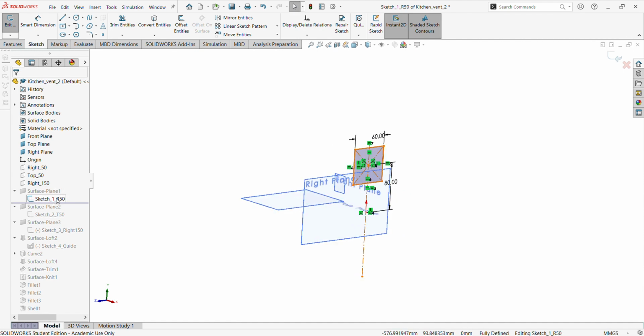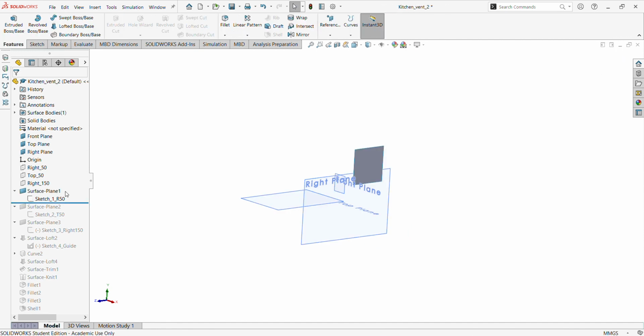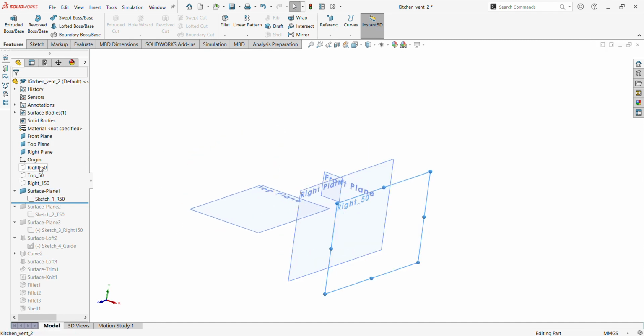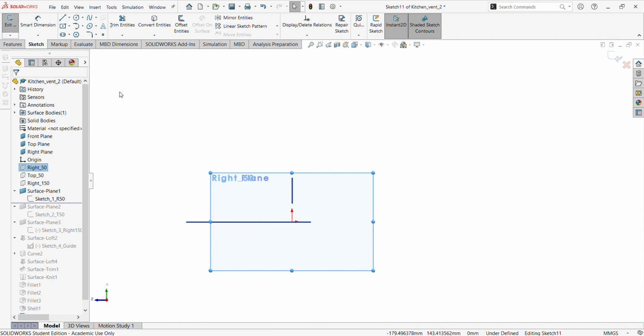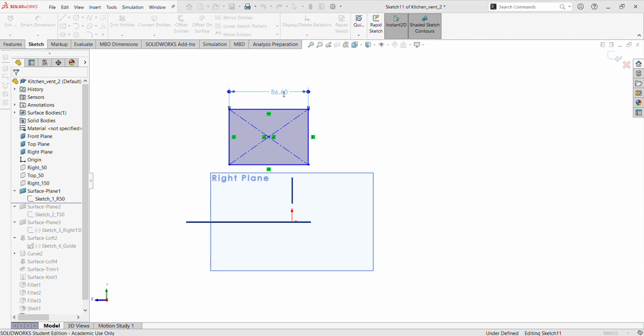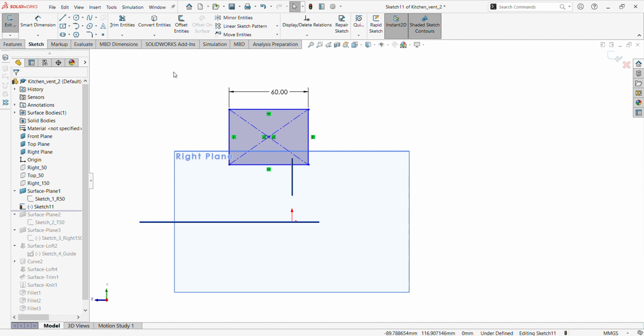If you wonder what I've done, I simply go to the offset plane. If I hide this sketch, you see quickly what was done, so we can save time. Hide the sketch. Okay, that one was not yet hidden. Just go to the plane here and create a new sketch, dimension it to 60, and make all the sides equal. Then place this exactly.